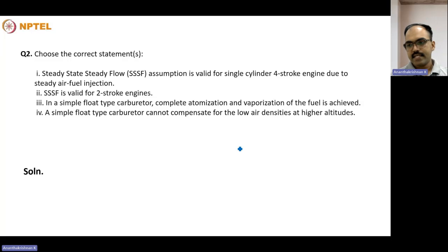So what do you mean by steady state, steady flow assumption? In this case, it will be steady state. That is, the properties won't vary with respect to time, like mass, volume, and temperature. These won't change with respect to time. And in the case of steady flow, the velocity and similar flow parameters won't change with respect to flow. So these two combined together, the flow parameters, just like the velocity, won't change with respect to time. So this means that all the parameters remain the same with respect to time.